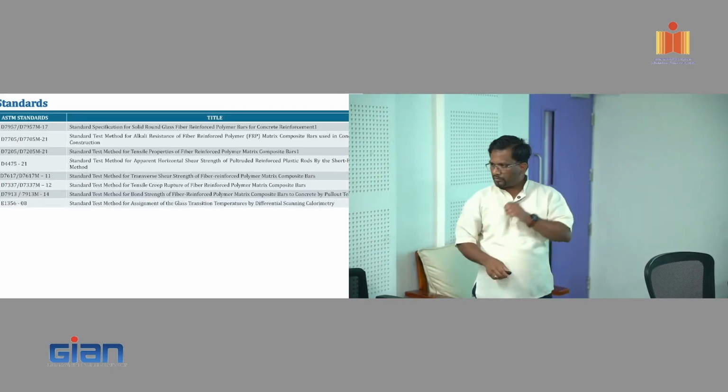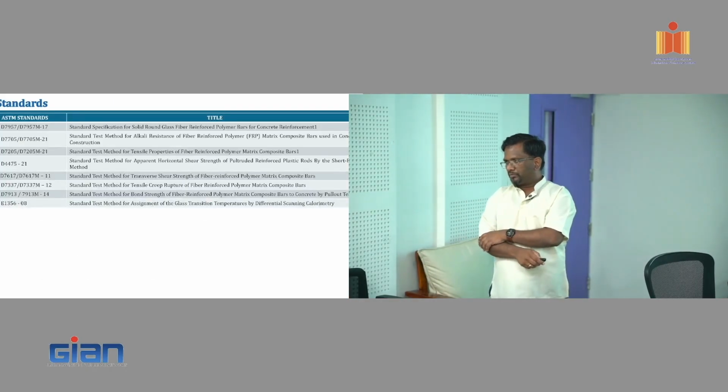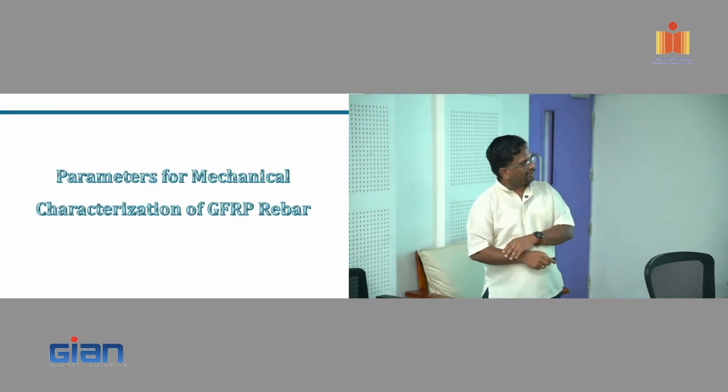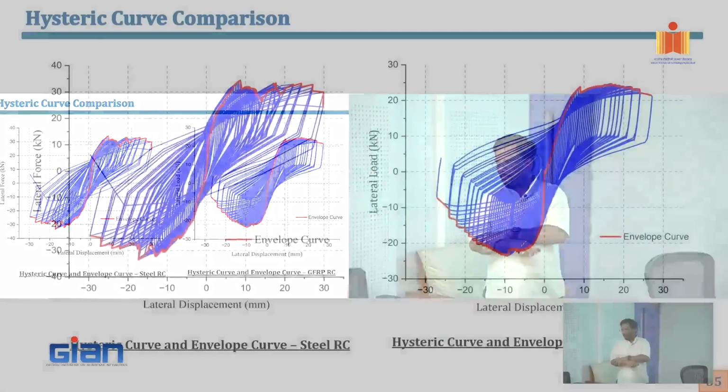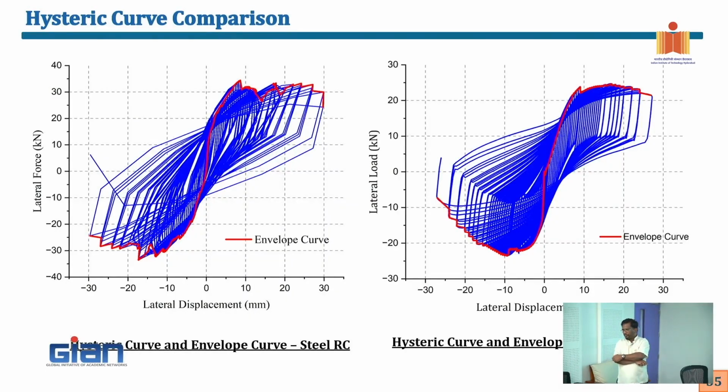By seeing the stress strain curve of GFRP, how will we decide what is the post-elastic region and what is the pre-elastic region? What's the elastic limit exactly? For GFRP rebar, everything is under the elastic limit only, so there is no post-elastic limit per se. You have to look at it at the section level. What you are saying is a material level response.